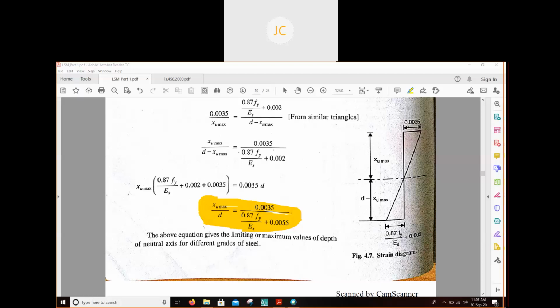Okay, so it is the maximum depth of neutral axis which we can allow to get an under reinforced section. Just simple meaning is that it is the maximum depth limited to ensure that the tensile steel will reach the permissible stress before the concrete fails, because under reinforced section is always preferred over reinforced section.